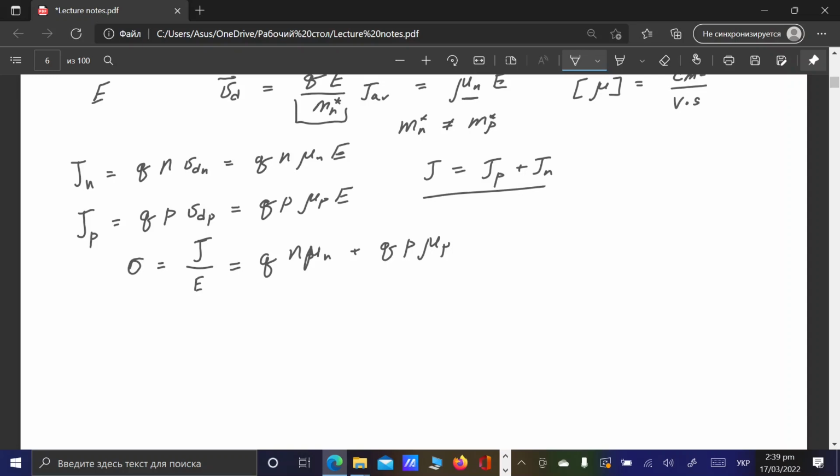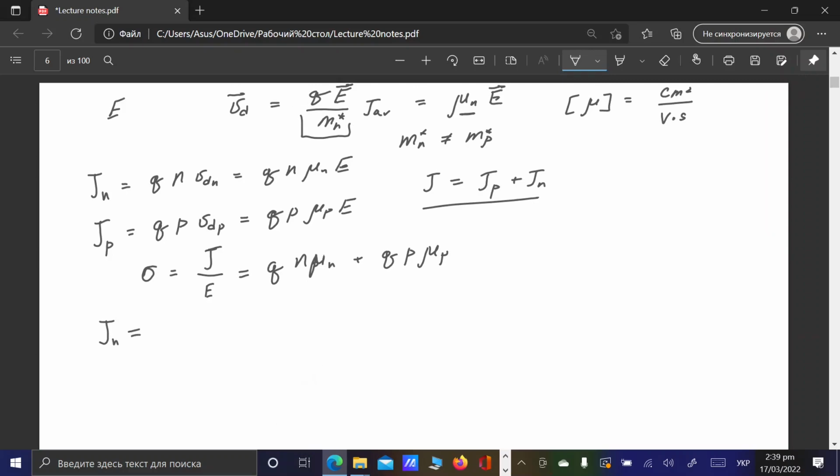So, in case of diffusion current, Jn carried by electrons can be expressed as charge of this electron times so-called diffusion coefficient, which describes some kinetic features of charge carriers in the material, how easily they can actually move there, and times first derivative of charge carrier concentration along the direction which we consider for studying charge transport.